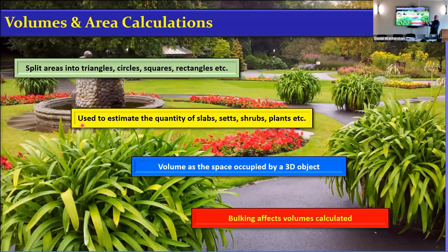That finished article needs a lot of work on it for 30 or 40 years of life to naturally compress. So when you're ordering your 10 cubic meters of topsoil, you need to ask for 12, 13 cubic meters, because it's going to compress. You ask for 10 cubic meters, they'll give you 10 cubic meters, but it'll be bulk 10 cubic meters. It won't be compressed, a nice block of 10 cubic meters.